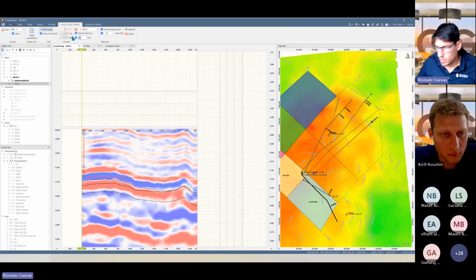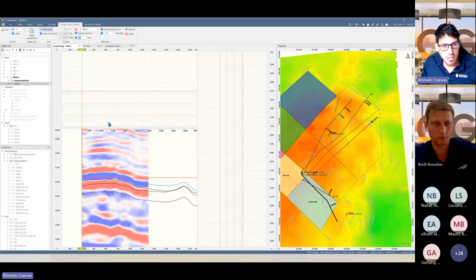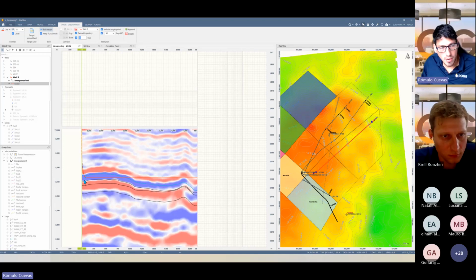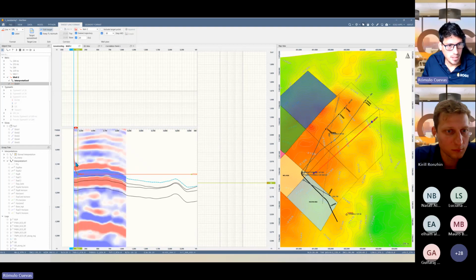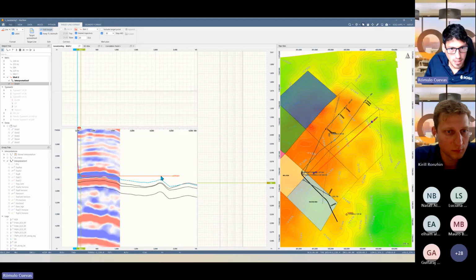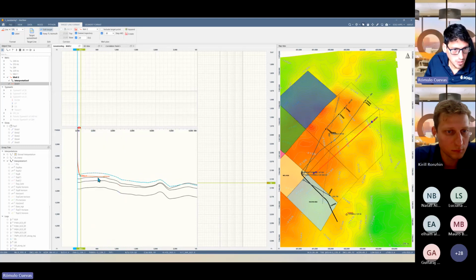And I can again customize here the dog leg. But instead of adding all the data points now, I'm going to add data step by step, just to build the trajectory inside of this reservoir. So I'm going to exclude the target line point and just add data till this point, for instance. So I can just append. I'm appending till this point here. Okay, and I can take this as a target line. Let me make it shorter like this.